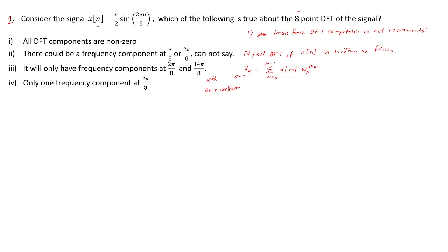If you remember from the lectures, DFT basically takes an N-point input vector of dimension N and does some processing with the DFT matrix, which is of size N cross N, and it provides you an output vector of the same length, that is N. So X[k] we denote as the kth DFT coefficient. It's just a weighted combination of these symbols x[n].